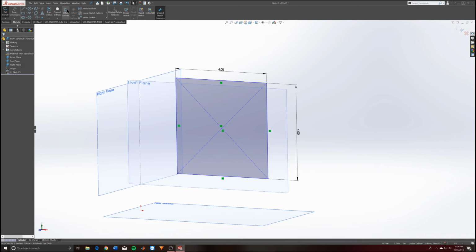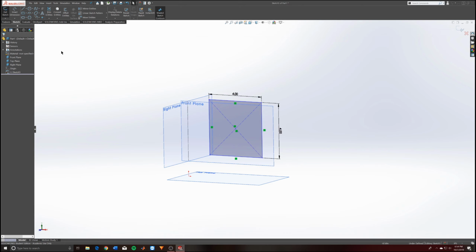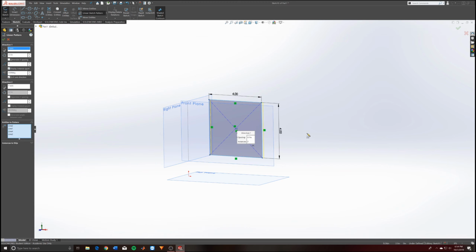And there's a few other things that are pretty useful. These are patterns for sketching, so if you want to make a linear pattern of your sketches. So for instance, this is your direction 1, direction 2. The X-axis is your standard choice, essentially right from the beginning. It's your default, and you can delete this line and choose Y direction if you want.